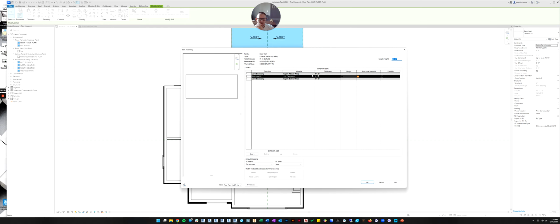So again, we just have a 6-inch generic wall. So let's think about the layers we want to add. On the inside of the wall, and remember the bottom of this panel is the inside and the exterior side is the top. Remember we want to add chipboard there. So let's insert one layer and let's move it down to the outside of the wall. That'll be our chipboard. So chipboard's 1/2 inch. So let's put in 1/2 inch.